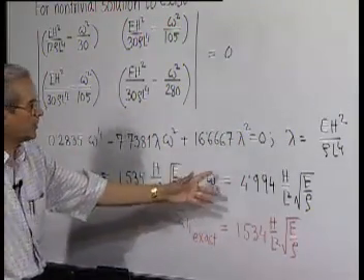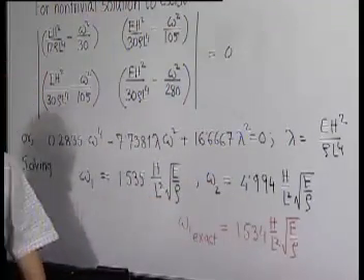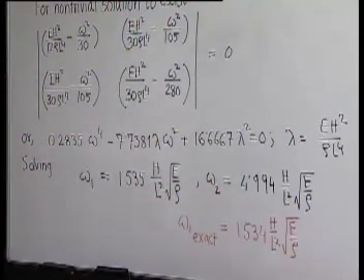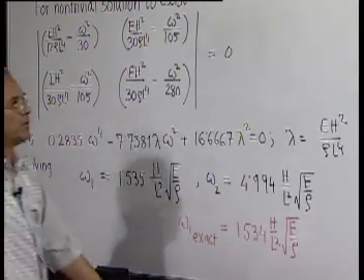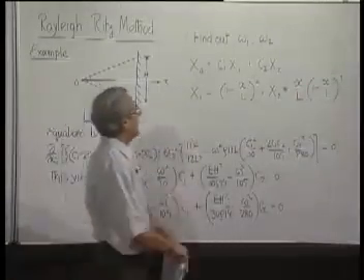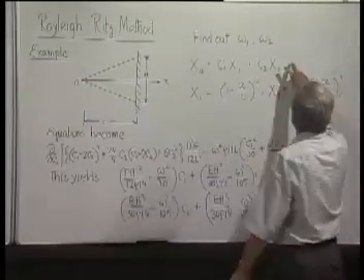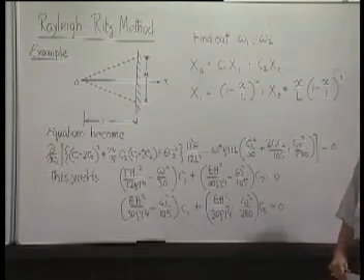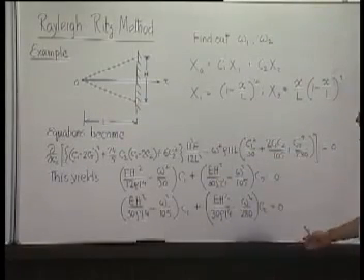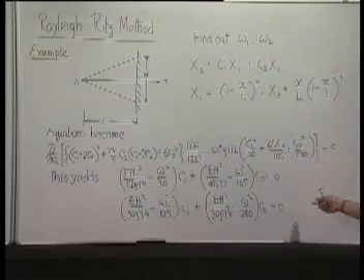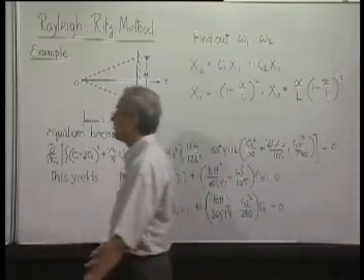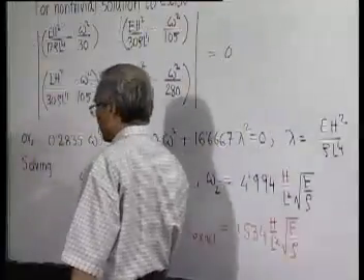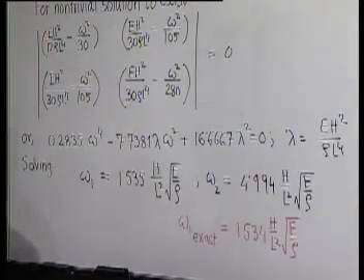The accuracy of the second mode has to be found out by analysis, but it can be shown it is also reasonably accurate. We could find even higher frequencies; only then it will be necessary to add one more term here, like C3 X3, and take X3. Obviously, computation will be more. There will be 3 equations in C1, C2, C3, and the determinant will give rise to a third degree equation in omega square, so it has to be solved for the roots.